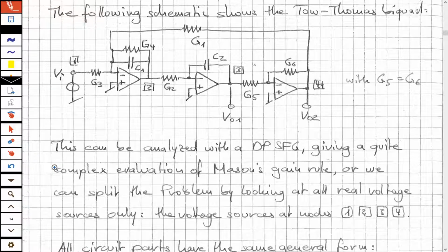And already you can smell that this is also an integrator loop, because that here is the standard integrator with a resistor and a capacitor in the feedback. That here is also a standard integrator, but because it also has a resistor in the feedback, it is a lossy integrator instead of a lossless integrator. You have a feed-forward path, and you have 2 feedback paths with resistors.